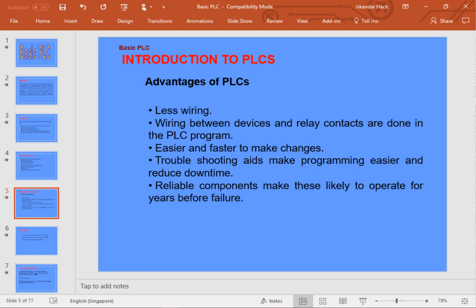And the failures had nothing to do with the logic. I determined after about 3 months of digging into it. But it was one of those stands, an old stand, been around for a while, and it was all done with mechanical relays. While I was at it, I converted it over to a PLC type controller versus relay, simply to make it more reliable. So again, there existed factory automation before the time of PLCs.